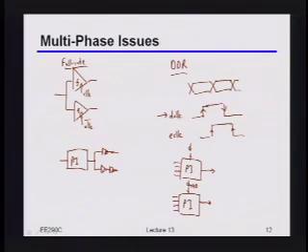Yeah, mismatch, right? So the obvious one is that, first of all, even if they were all the same phase interpolators I had before, they're going to just burn more power, right? Just linearly with the number of phase interpolators. Now that's not exactly true because the frequencies maybe aren't fixed, but roughly speaking, power and area goes up, right?